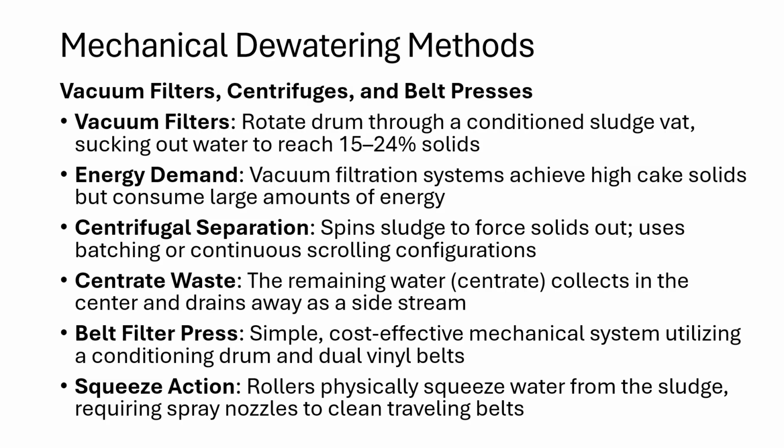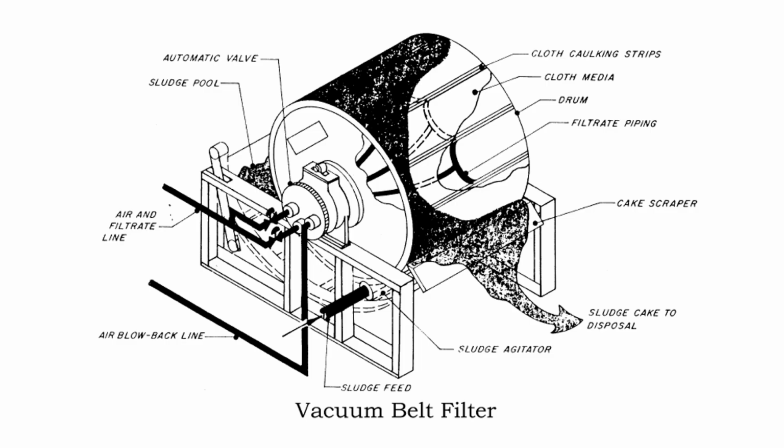It's actually fairly effective. Okay. But the water that's squeezed out of that sludge, you can't just discharge it. You can't just drink it. You can't sell it. You've got to take that to the headworks. Its drainage is piped to the headworks, and then it comes back in again, typically high BOD and low oxygen on it. Okay. And this is what one of them looks like.